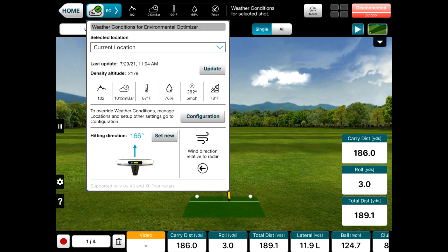And then from that, we calculate something that we just published there for people that know what it means. It's called density altitude. So density altitude basically means that we compare the actual weather conditions and air density to sea level, and we will tell you that effectively, say in Orlando today, it's playing 2,000 feet and not 100 feet, something like that. Why is that? It's a combination between air pressure, temperature, and the relative humidity.